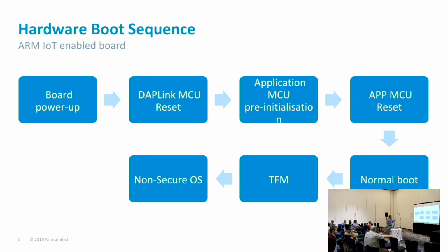Yes, but we will always need to test hardware. So the question is, if we don't have a DAP link, we would need to have something that mimics certain functionalities of the DAP link. The most important things of the DAP link are functionalities like drag and drop flashing, or exposing the serial controller. This could be done by external hardware.